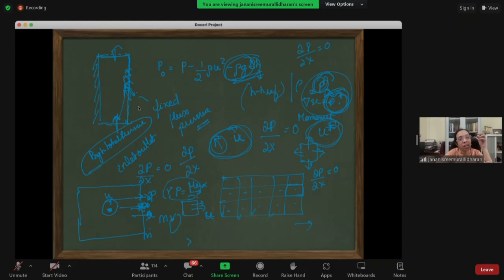Okay. And understand the kind of velocity fields you are seeing. Okay. And then you calculate a CFL number roughly, because it's going to be basis your grid size, purely basis your grid size. So then you estimate a CFL number which is coming basis the velocity field.